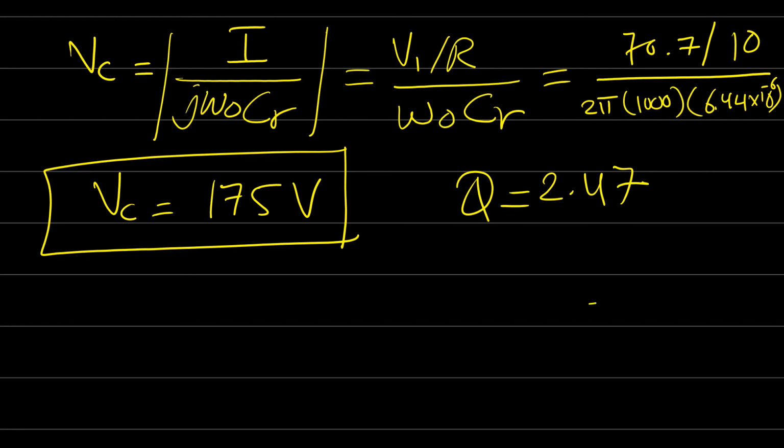So let's say, for example, your voltage on the output is 70 point something, or on the input is 50 point something. One of the problems in a resonant converter is that, yes, we can cancel the effect of the capacitors and the inductors, but the voltage tolerance, or the voltage stress across these elements, must be large to be able to handle the resonance effect.